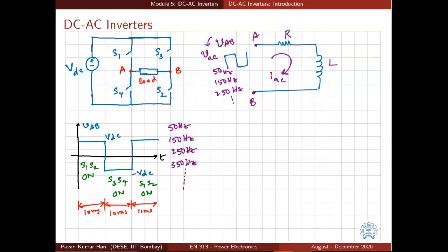As we know, when we say we are applying a square wave voltage, we are actually applying sinusoidal voltages of infinite order. So we have many sinusoidal voltages being applied, and the most significant ones are 50 Hz, 150 Hz, 250 Hz, and so on. Now we know that from the superposition principle, we can arrive at the frequency components of this current.